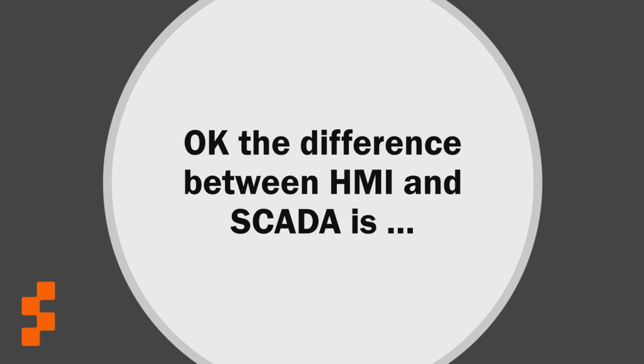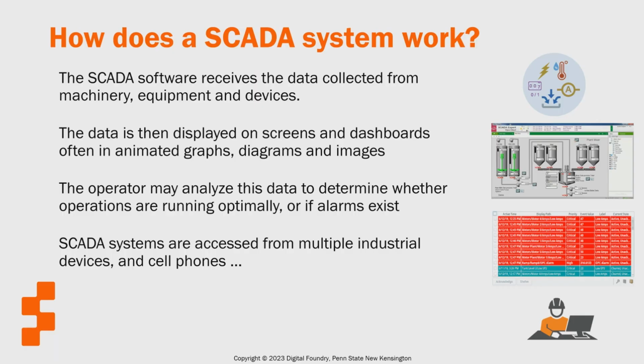monitor machines, while SCADA, on the other hand, is designed to provide more comprehensive monitoring solutions over larger networks of connected machines. HMI usually does not store data, but SCADA has a historical server that can contain its database. An HMI, for example, will be placed on the control panel near a part of the machine, where a SCADA would be set up in the control room far away from the machine itself.